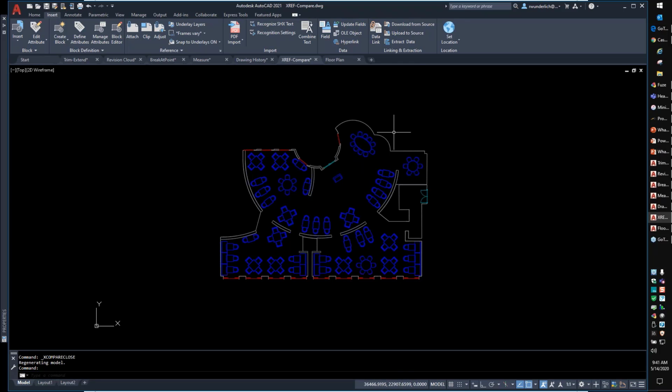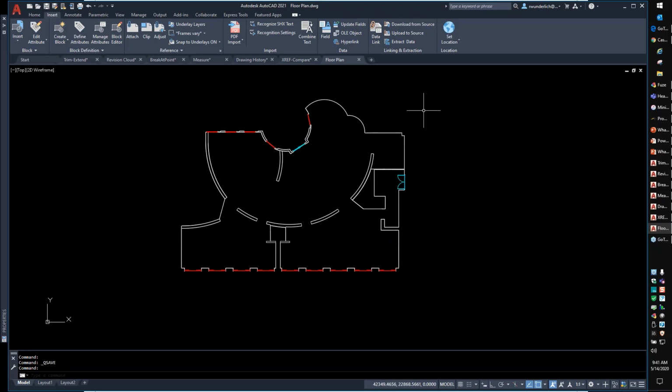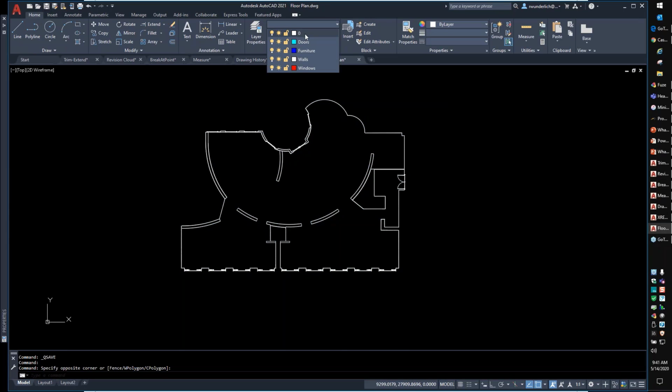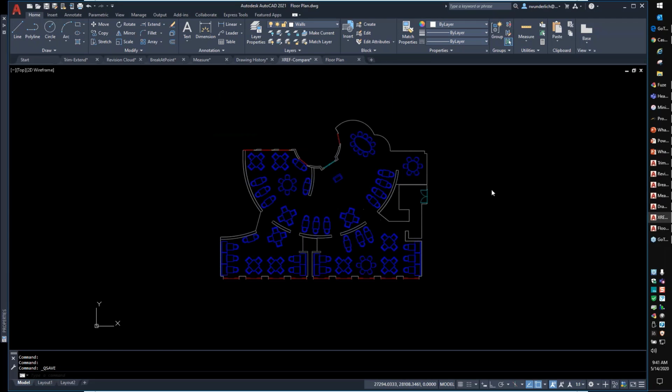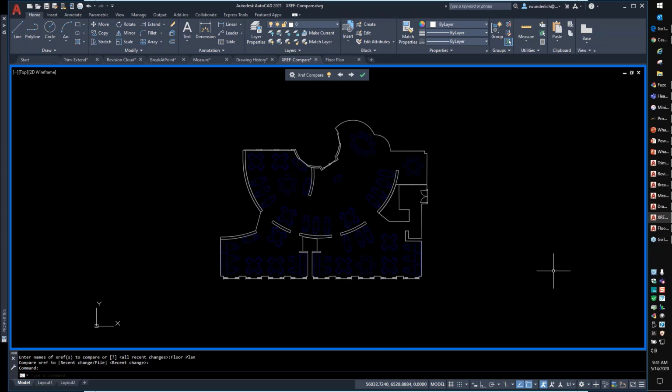So this will pick up geometry changes, i.e. lines, arcs, circles. Text is a geometry change. Hatch patterns are geometry change. If I change something here, so for example, I move all of this stuff here, right? So I'm on multiple layers. Let's just say I move everything to layer 0, okay? And I save this, and I go back to here, it's going to tell me this changed, right? No changes. It did not pick up any changes because none of the geometry changed.